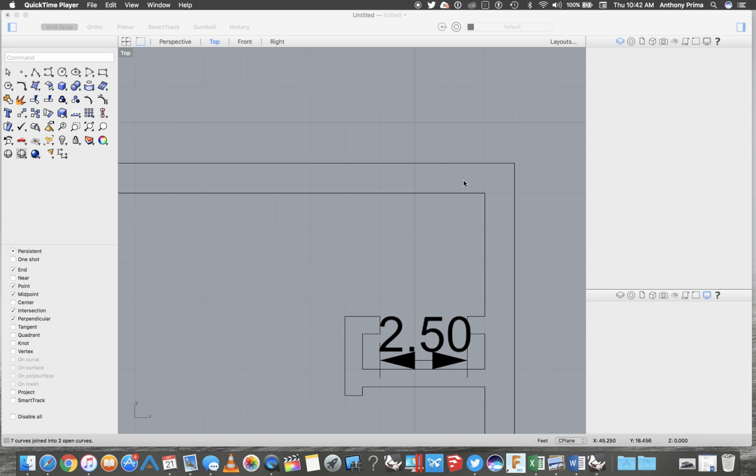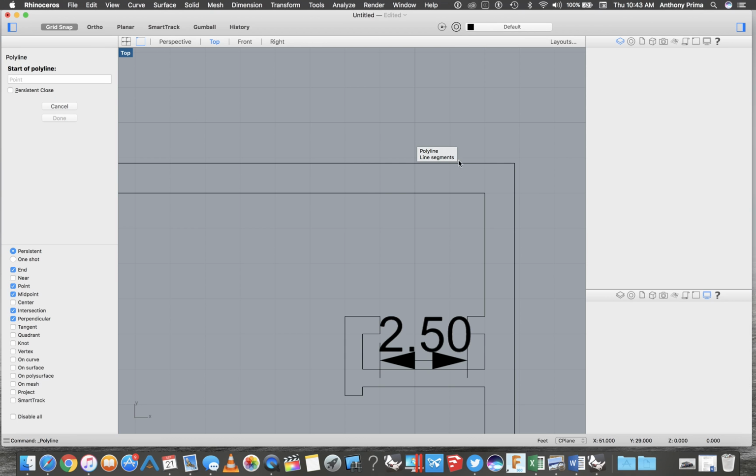But in this video here, we're going to go over creating a single hinged door, what that symbol will look like, and how to create it. So the last one we used the box tool. We could do it the same way, but for this one, instead of using the 3-point box tool, we're just going to create lines because again, we have our grid snap tool on, so it's really easy to see where the measurements should be.